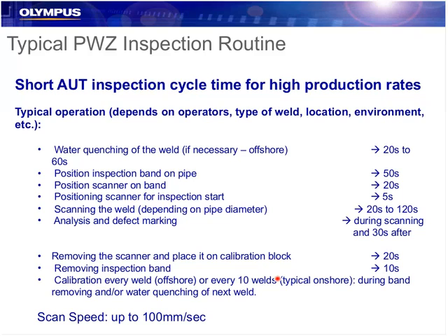Offshore, we do that every weld because after it runs through manufacturing, then inspection, it often goes directly to be placed underwater. So obviously, it's much harder to retrieve or fix. So we usually do one weld, one calibration block, one weld, one calibration block, and record every one of the calibrations to show that our inspection process was good.